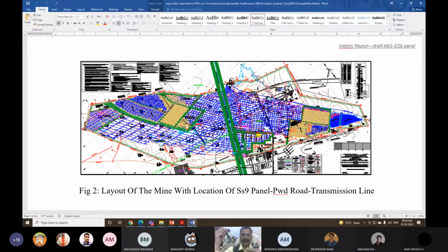So apparent dip, and then other galleries when I am making them in this fashion along the strike, now my pillar will be a rhombus shape like this instead of a rectangular or a square shape. So these are the ways that we design based on the geology and the orientation of the deposit itself. When it is steeper, that's what is happening here in this mine. And now here, how we divided that.